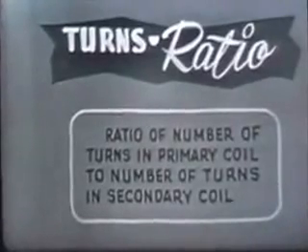For example, if the primary coil has 500 turns and the secondary 1,000 turns, twice the number of the primary, or a ratio of 1 to 2, let's see what happens to the voltage. Presto, Mr. Volt became twice his size. The ratio is 1 to 2, so the voltage doubles.